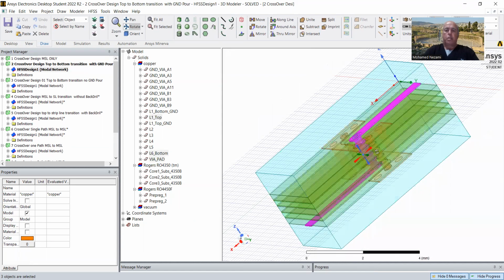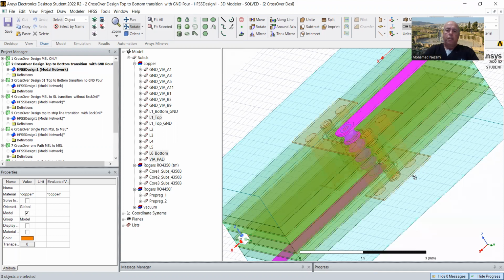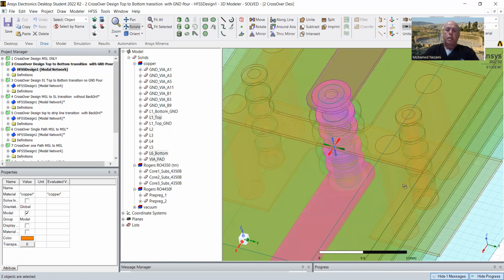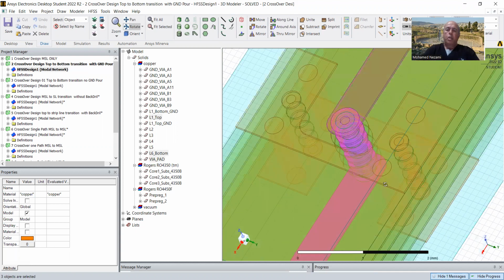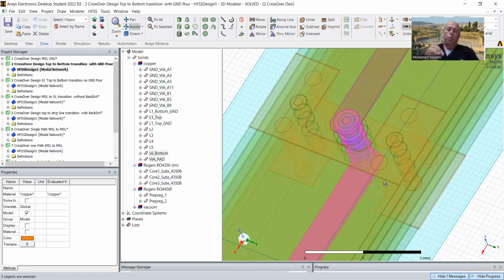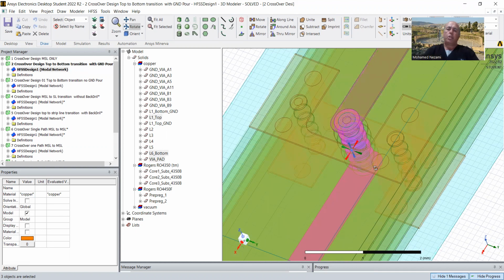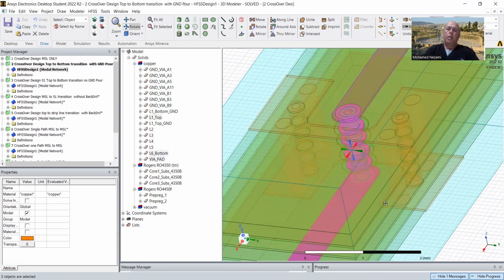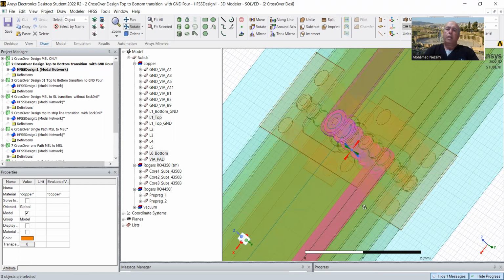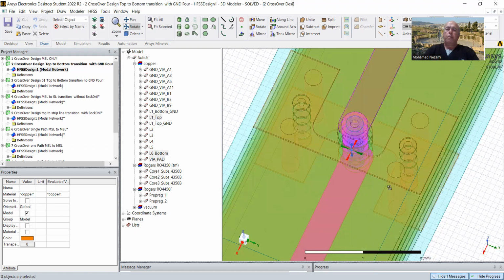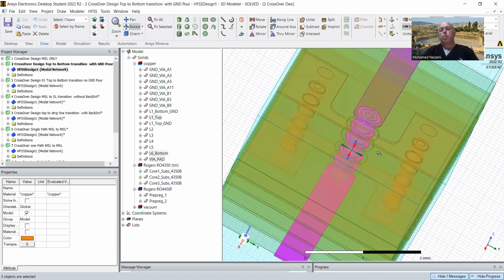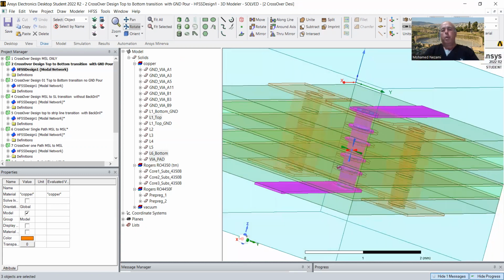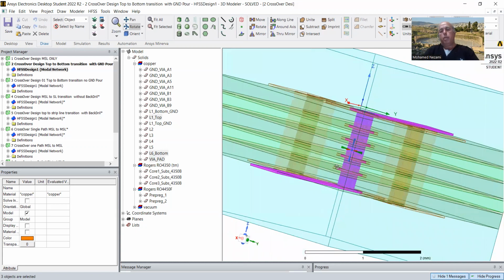In this way I designed the via, which is basically 2 cylinder metals, one smaller than the other, and you subtract them so you get the finished drill hole, and then you make the pads. Basically, at each layer there's a ring pad, and then the anti-pad as well. You design that. If you come to my training, we will go through these exercises. So this is basically what this is doing.